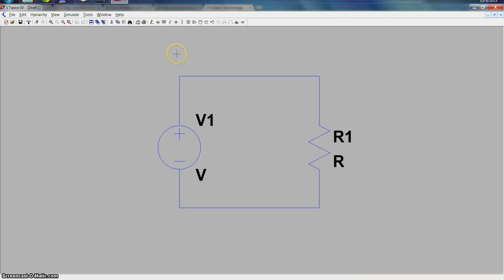Okay, the next thing you need, and you need this for any circuit, is a reference ground. A ground is just where the 0 volts is in your circuit. You can define that anywhere. Actually, there's nothing wrong with defining ground up here, but for simplicity, you usually want to put it on the negative side of your voltage source. So then I'm going to draw another wire, and by the way, there are hotkeys, so if you see me doing anything really quickly, it's probably because I knew a hotkey for it. I'll try to talk about those as I go through.